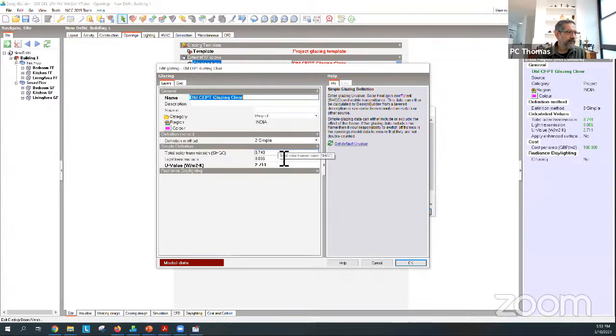So if you have a solar heat gain coefficient, that tells you how much solar radiation that's hitting the glass perpendicular is going to come through the glass. Okay, and then for every hour, the model will adjust how much of that actually enters, because the higher the angle is, the higher the reflectance is. Then the light transmission obviously is daylight, but the U value is quite impacted by whether you have 1 piece of glass or 2 pieces of glass.